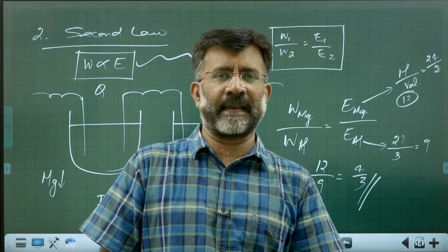Right? And all impurities present in this metal will be sedimenting over here. You are remembering, I believe it is called anode mud. Anode mud is not simply impurity, it contains valuable metals, as copper is always contaminated with atoms of gold, platinum, antimony, tellurium, etc. Costly, precious metal atoms we can get from the anode mud.